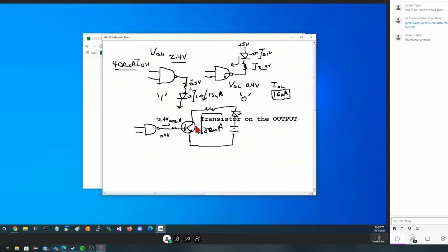So we didn't talk about in here the opposite of this transistor. We're using what's called an NPN transistor. If we really wanted to do this right, we would consider using a PNP transistor. Now, we're not going to study those right now, but just be advised that we could get the job done with an NPN. A lot of people do. You see a lot of projects online where they use an NPN transistor, and they're not really thinking very carefully because we're right borderline on not being able to do this because of this 0.4 volt value we could get for ground. So a little more designing would have to go on.